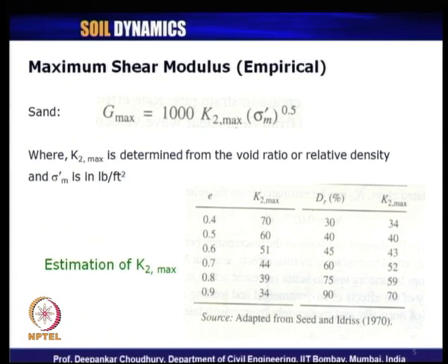Another caution is that these empirical relations were derived by several researchers, and though mentioned for sand, they may be valid only for the local regional soil. For a particular soil, it may be valid. For other regions of soil, it is still questionable whether it will be valid or not. That needs to be checked.